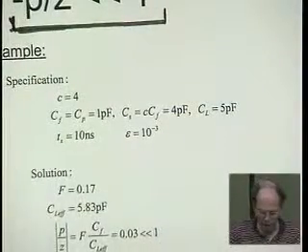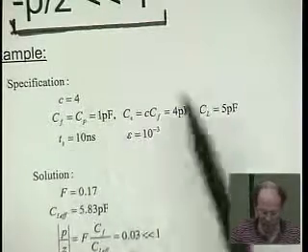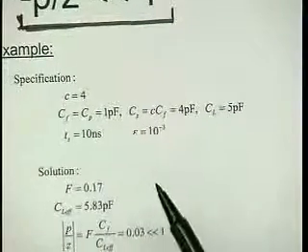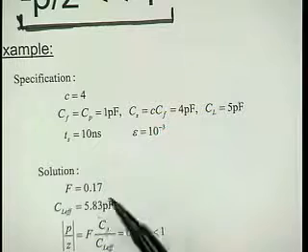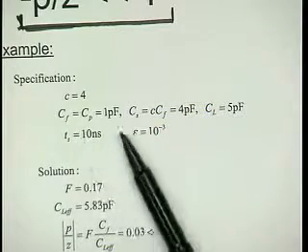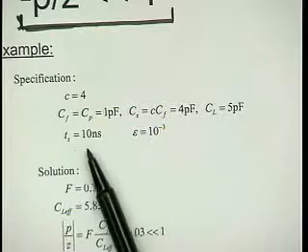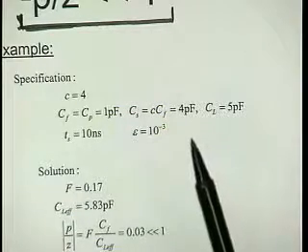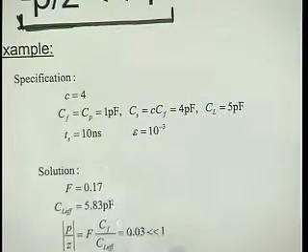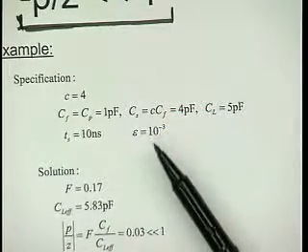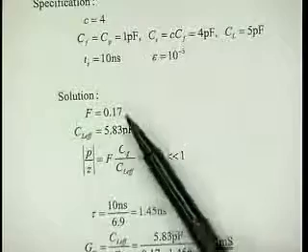Okay, so an example here. We design, again, this thing with a closed loop gain of minus 4. Again, I've chosen some capacitors that give us this. Now my settling time that I allocate is 10 nanoseconds again, as some A to D or whatever application sets that. Accuracy 0.1%. I calculate the feedback factor.